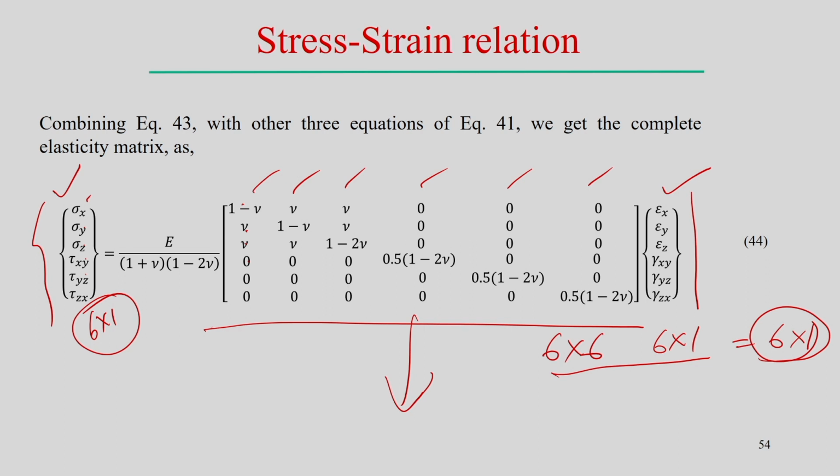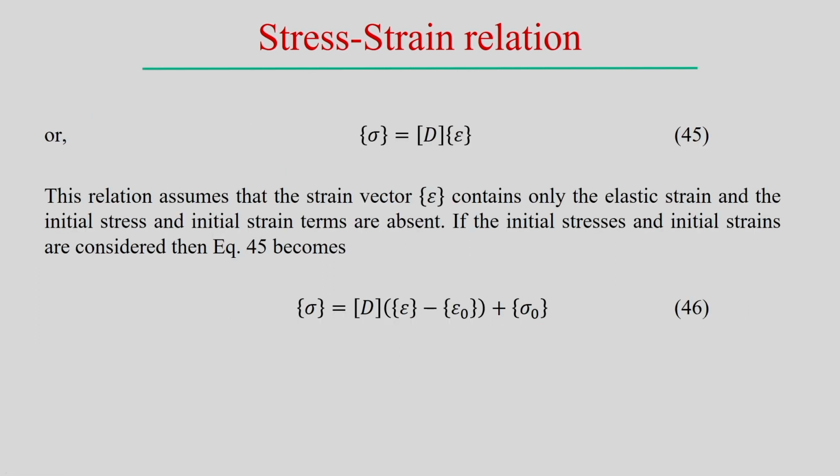we have already shown the 2 dimensional case also. In 2 dimensions the expression will be different, but the nature of the equation and the number of constants involved will be the same. Now, stress strain finally relate as stress equal to D into strain. D basically takes care of all this accounting, and it is associated with the material properties. So, basically Young's modulus and the Poisson ratio, and the form or shape of the D matrix will be different in case of 2 dimensional or 3 dimensional.